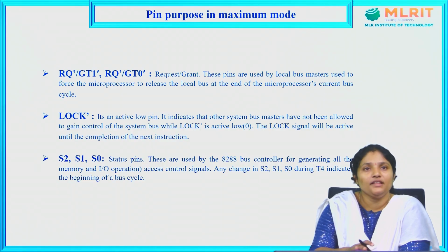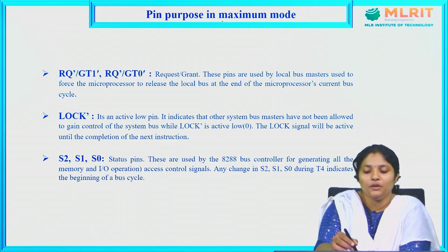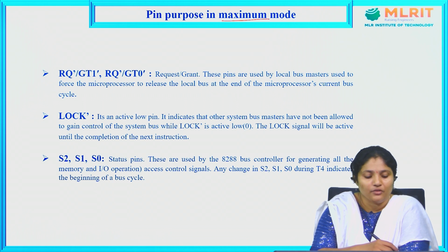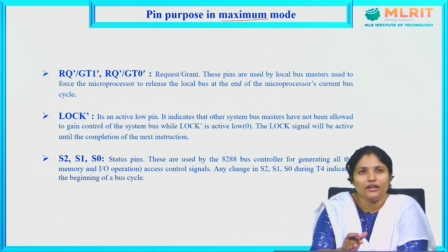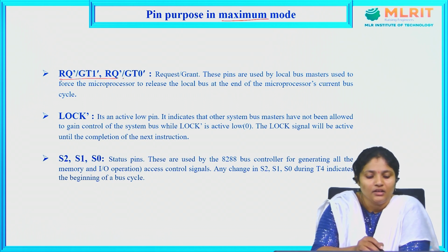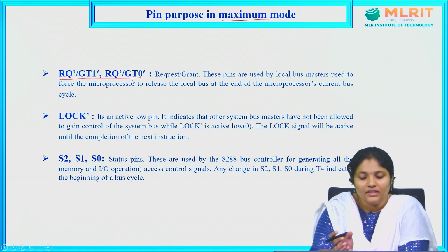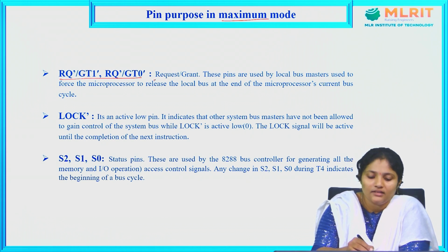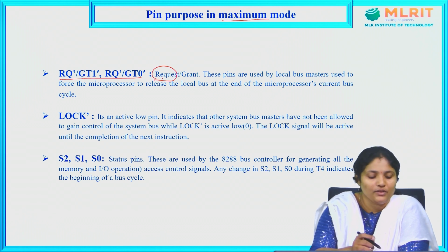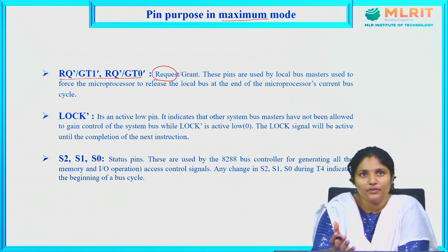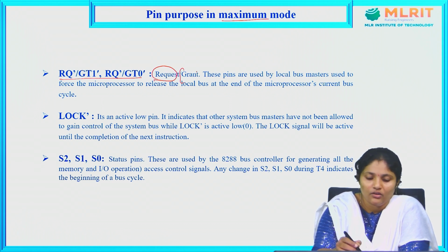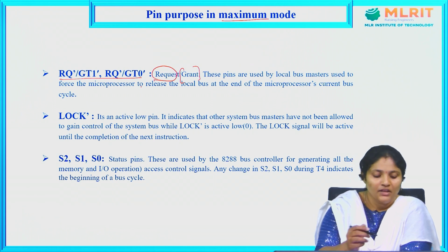So these are the pins which are used for the maximum mode microprocessors. The hold and hold acknowledgement will be related to this. If the other peripheral devices want the system bus, they will ask the processor, sending the request through RQ bar. And the processor needs to grant the request or send the acknowledgement, which it does using grant GT1 and GT0.